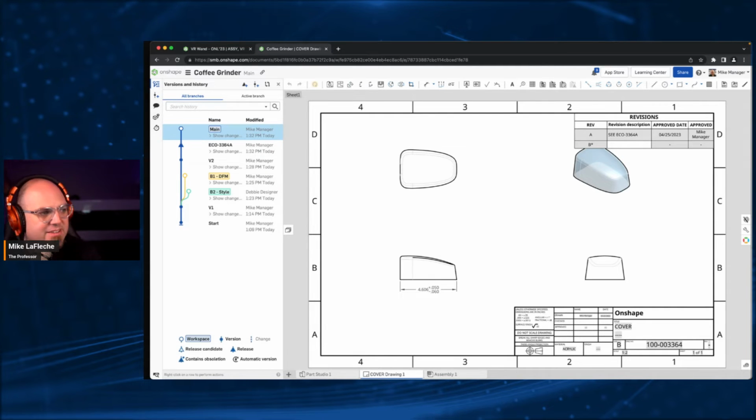So hopefully, you saw the conflicting message thing, right? I saw the question here again, just on the merge conflicts. Just want to make sure we understand that from before. The merge conflicts is never really a conflict. A change could happen. A change could break the feature tree. You would need to go in and either edit the feature tree or just revert before the merge happened. Really, those are your two options there for merge conflicts. All right, anyway, we're going to keep going.